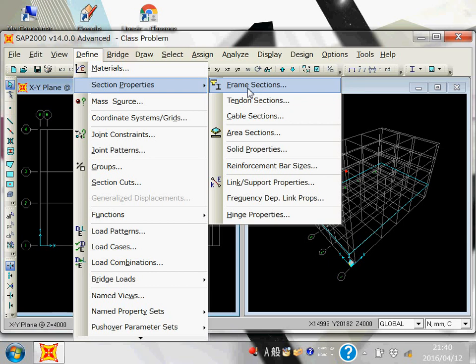Because when you use a bigger size for a small building, what will happen? But how will you come to know that you have selected a bigger size? By trial, every time you place it. If you select a bigger size for column, you will get the minimum reinforcement always.